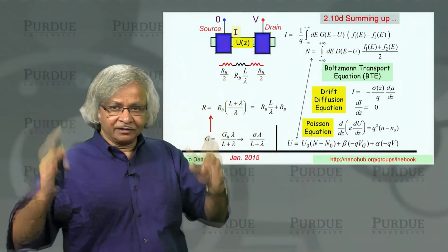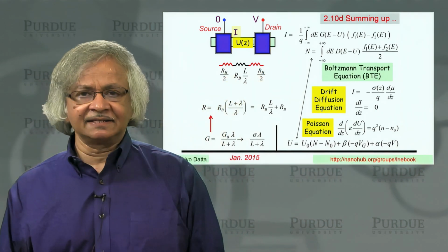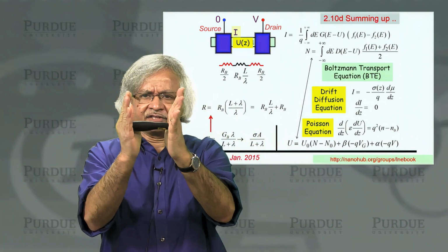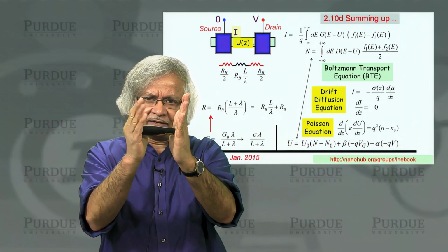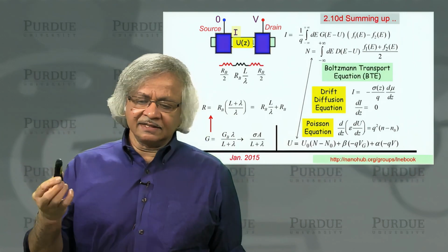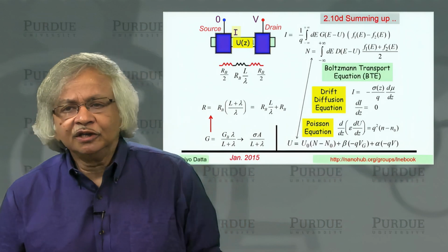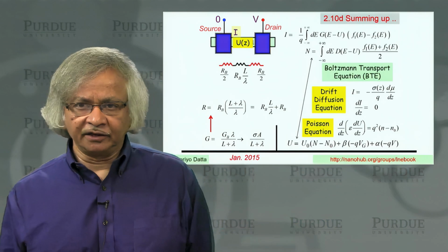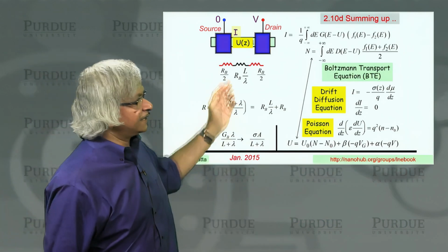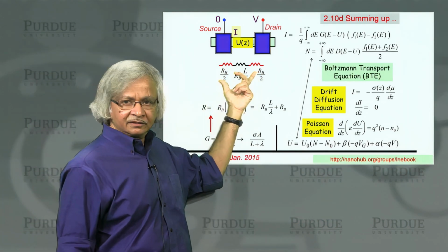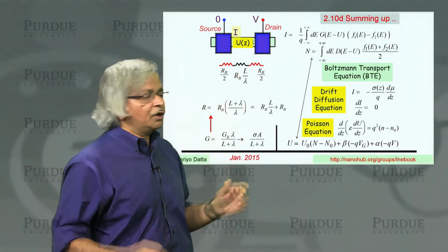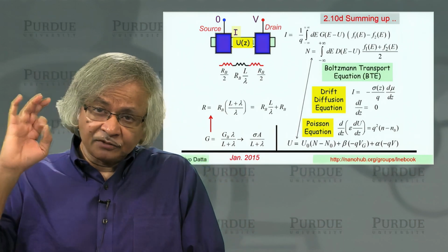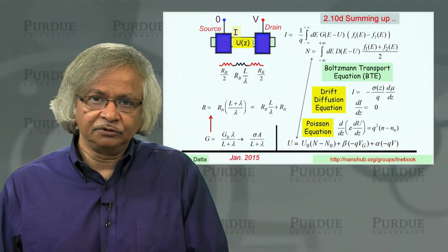I mean, that is the important thing, that what everyone realizes is that if you had a small conductor or any conductor, you always have contact resistances or interface resistances at the end. What people didn't realize is that there's a fundamental limit to that. Usually you think that if I can improve the quality of my contacts, I can get rid of all contact resistance. What we know today is that that's not true. There's a fundamental limit, this ballistic resistance. And so your roadmaps of where you want to go, kind of devices you want to design in future, has to take those fundamental limits into account.